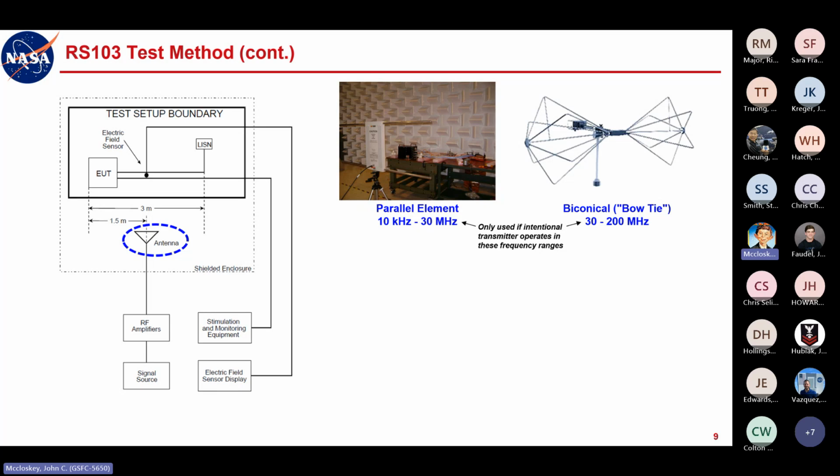We use our common mode conducted emissions and susceptibility test. So to emphasize this point a little further, recall the wavelength in meters equals 300 divided by the frequency in megahertz. That's just another way of writing c over f, the speed of light in free space or air, divided by frequency. C over f is just 300 times 10 to the 6th divided by frequency. So 300 divided by frequency in megahertz is just shorthand for that.